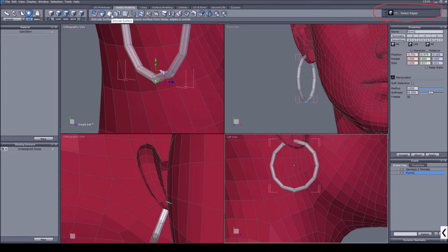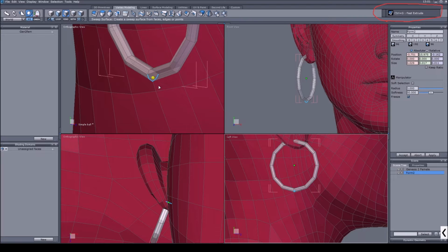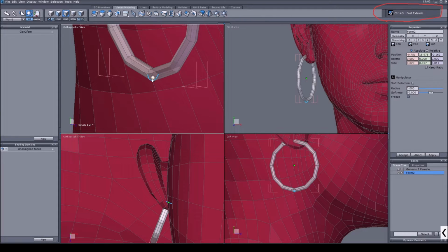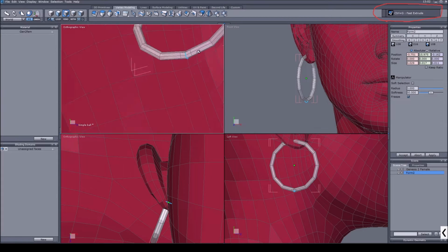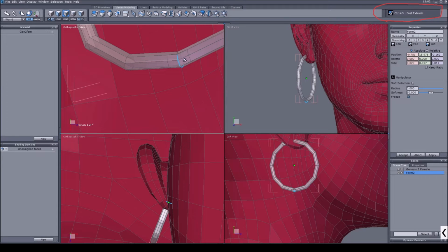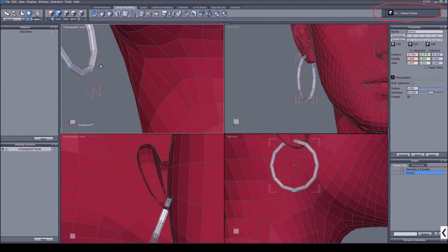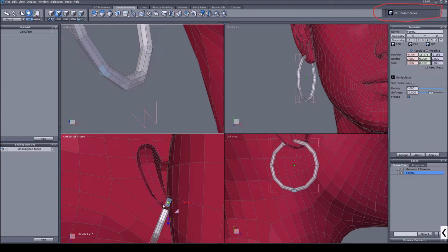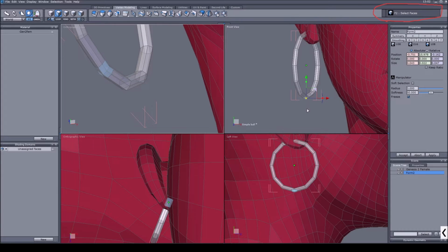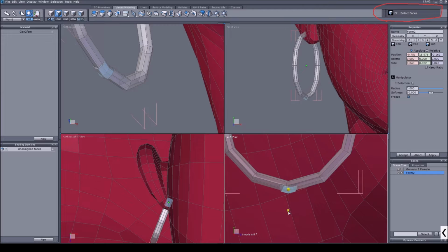And I'm using the extrusion tool, which is bound to Control G for me. And now if I just click once on the green ball, and then I stop clicking, I have basically segmented this whole thing. On the ground I have additional faces here around the edge that I just grabbed, and I'm going to grab these next. And this is basically what I want to work with. I'm going to pull them down just slightly.